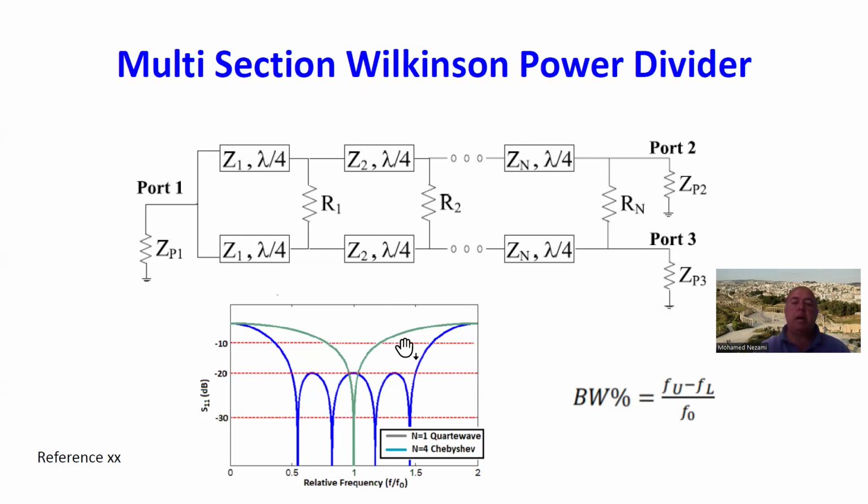So you might realize by now that we use multi-sections to get a broadband response, and that's illustrated in this diagram. With a single order one, which is basically this piece here, you might get some kind of response like this for the input return loss. But if you're trying to cover multi-octave bandwidths, you basically cascade a number of them, and that's what you're getting in here.